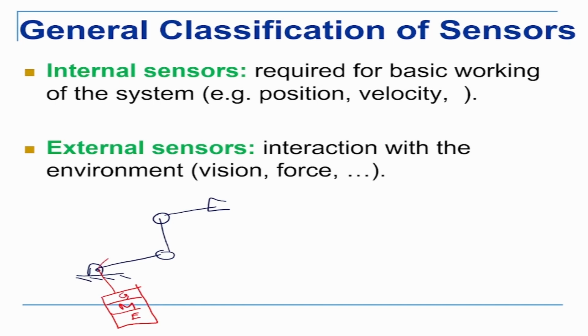Okay, and how does the robot move from here to here? Basically, if I'm here and I want to go there, it will do inverse kinematics and find out the corresponding thetas. Suppose theta 1 is equal to 20 degrees and theta 2 is equal to 60 degrees there. Then the controller understands that it has to give the voltage to the motor such that the link moves by an amount of 40 degrees. So it will do 60 minus 20 equal to 40, and move the link.